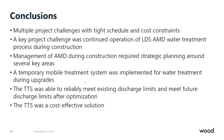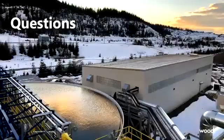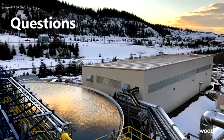So, a pretty quick process. And then during its operation, after dialing in, we were able to easily meet the existing discharge limits. And then we actually met future discharge limits for zinc specifically. Cadmium bounced around a little bit during operation. And then, at less than 3% of the project cost, it ended up being a reasonable, cost-effective solution for this project specifically. So with that, any questions?